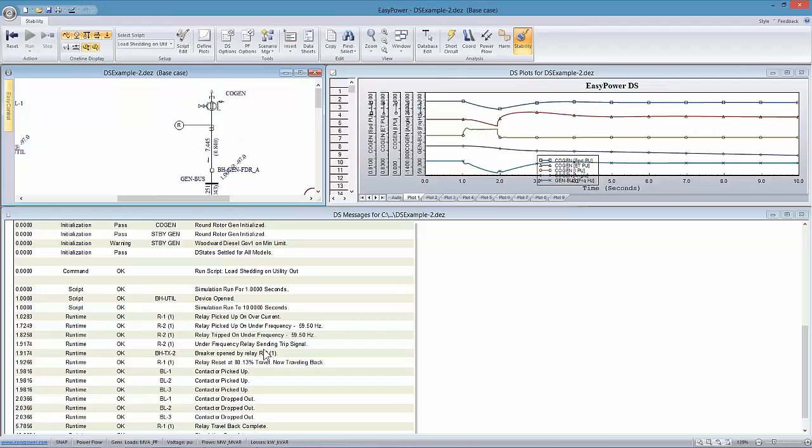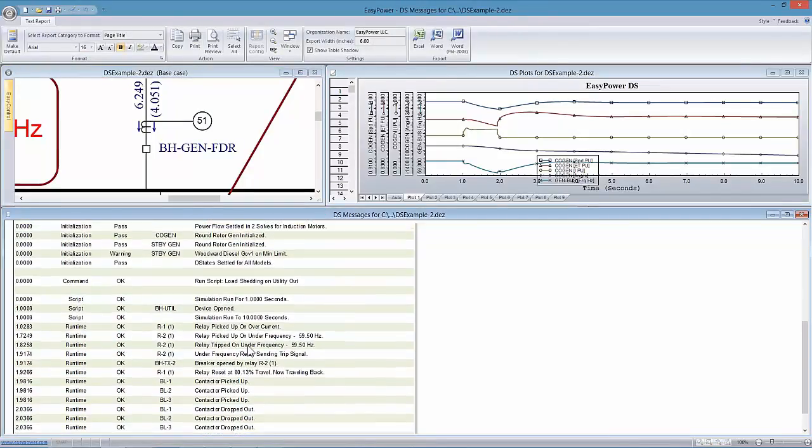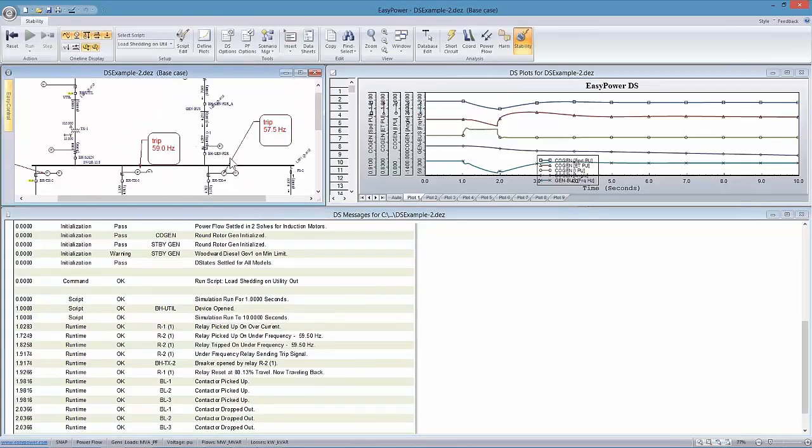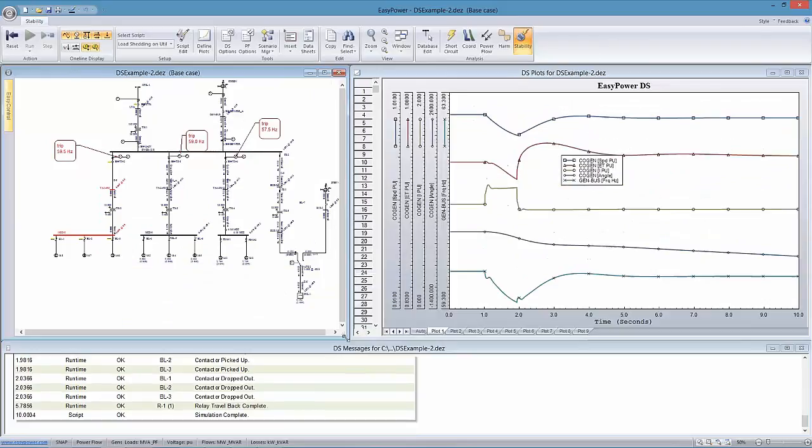So this gives us a step-by-step, and frankly I wasn't expecting the overcurrent relay to trip whenever we went into this exercise, but now that you think about it, that's pretty much what we're talking about, an overcurrent condition until the generator recovers. All right, so that's example one.